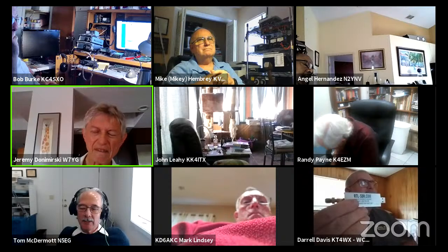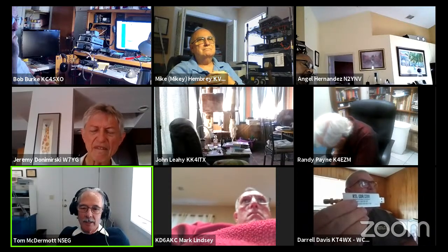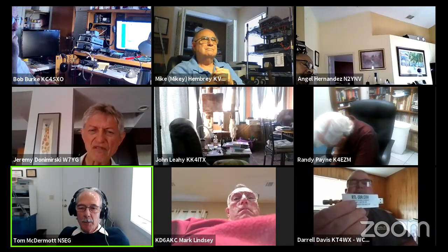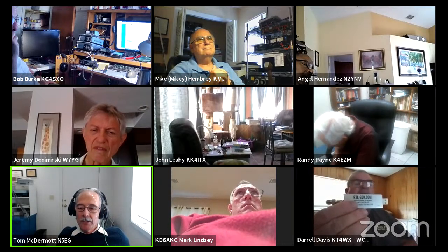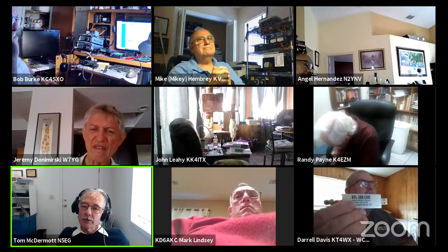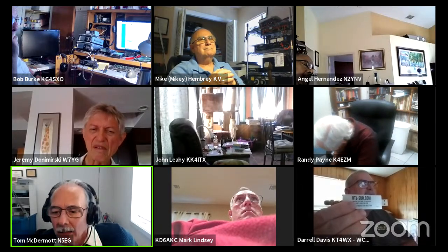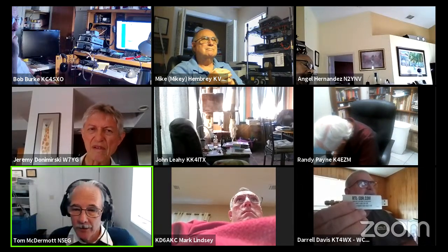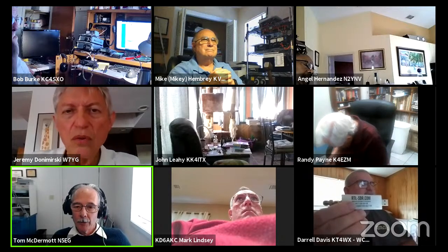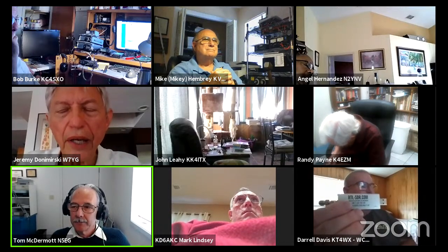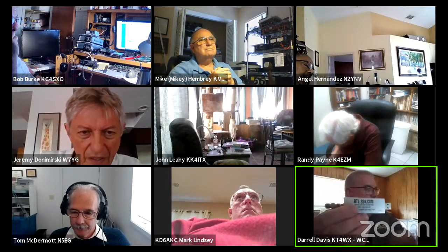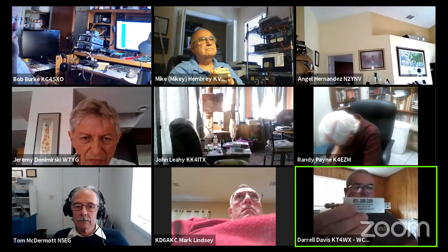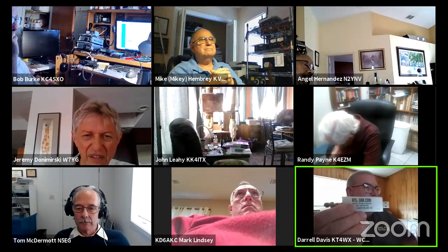You can see digital TV carriers, and you can see the broadband digital spectrum, and you can usually see the analog carrier. There are better versions of those available, and I think Daryl's holding up one of the better ones, with a little better performance. It's version 3. And you can modify it for HF too. You have to solder some jumpers, but you can change it to work on HF as well.